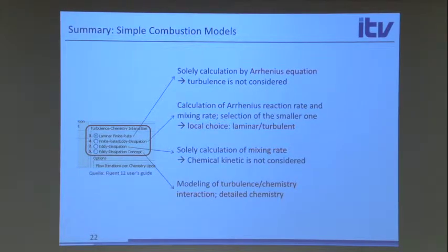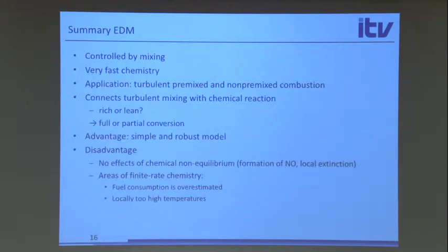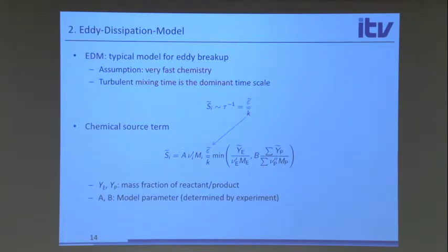One of the things that's interesting also, I forgot to say this, with this Eddy Dissipation Model, which originally was formulated for diffusion flames, is that this B here is just a model coefficient. How strongly should I weigh the product mass fraction compared with the oxygen and fuel mass fraction? That's B, and A is just a coefficient in front of the whole thing, okay?